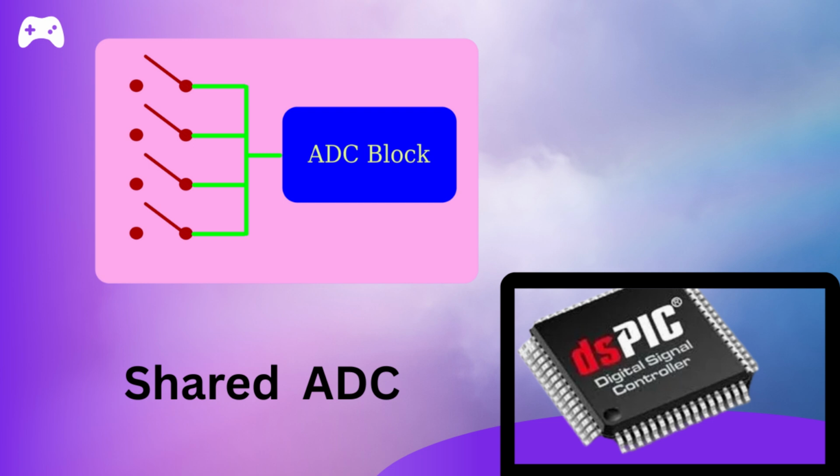So one at a time, one analog signal can be digitized at one point at a time. Then you can go to the next analog signal. Likewise, you can cyclically digitize any analog input. Also, you can do it in any series by controlling the switches. The switches are all selectable by software or firmware.